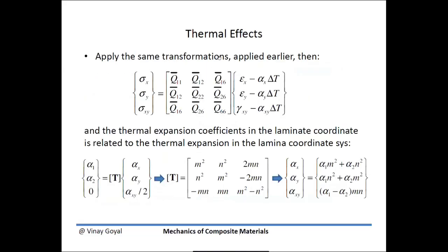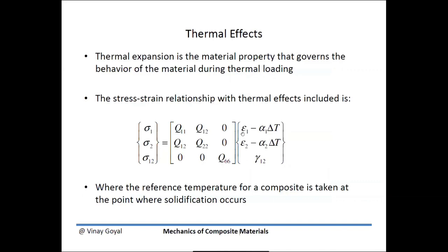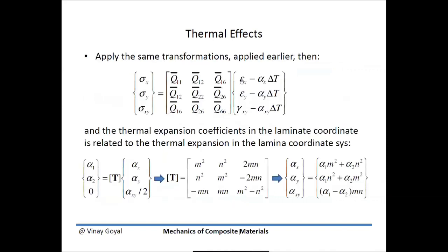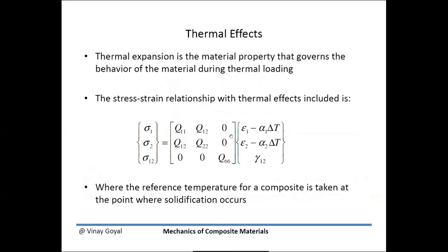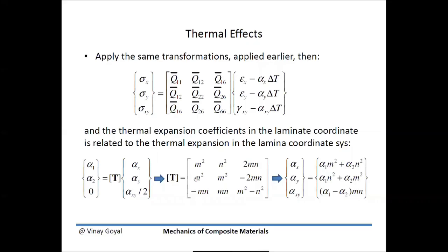So we can apply the same transformations we talked about before to transform strain to stress, but bring that into the global orientation system. And so this is what we get for that. The alphas here can also be transformed using this relationship here. So you can just use these formulas and you'll be fine. So alpha in the global orientation system can be related to the alphas in the principal orientation system. You get this weird alpha XY that shows up, but it's important to consider. Okay, so once you have alphas, that can be plugged in here, and now you're ready to go.